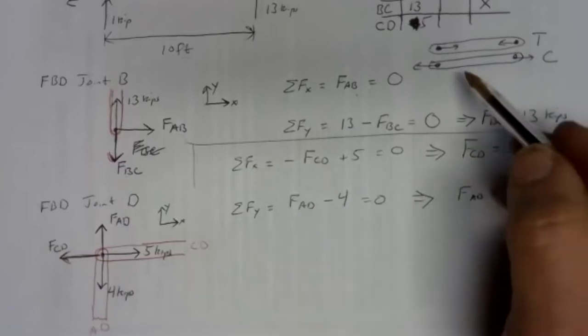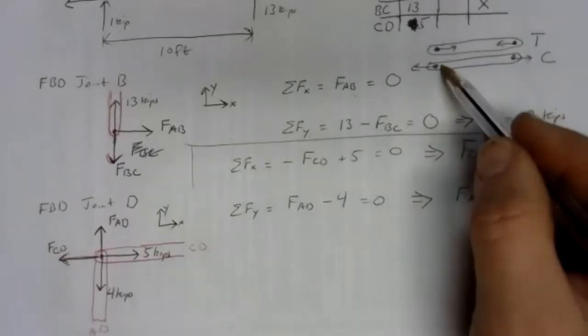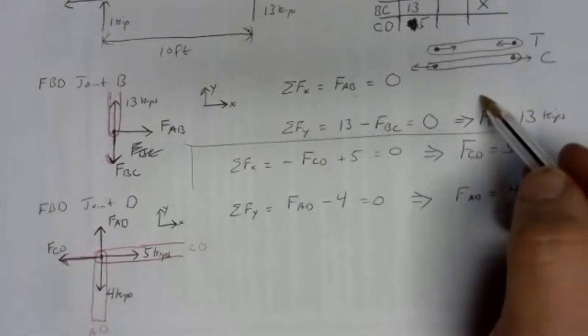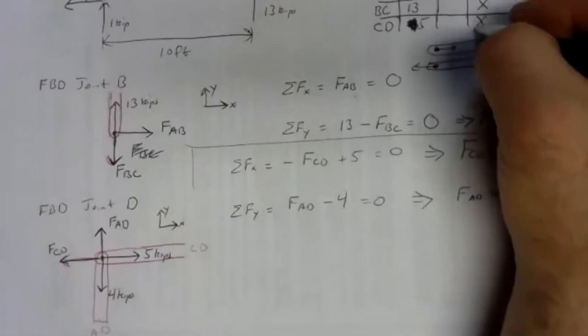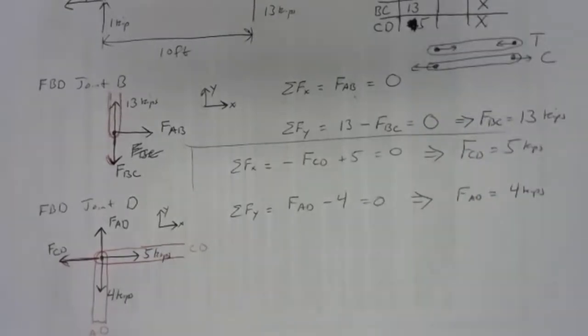So that matches up here with the left end of my compression beam. So this is also compression. So member CD is in compression. So far, everything we've looked at is in compression, which is rare, but just has to do with how we've loaded this and how the order I've worked things in.